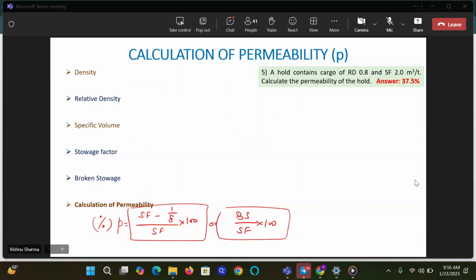Done, sir. Okay, it's 37.5% is the permeability, and then this can be put to use. So it is like a question giving you that permeability is 37.5%. Then you know how to put the given permeability, or this calculated permeability, to further use. I hope if it comes, you'll not mess it up, guys. Can I draw some confidence from it? Then you'll be able to take care of it. Yes, sir. Okay. Now, guys, we go to a very typical scenario.